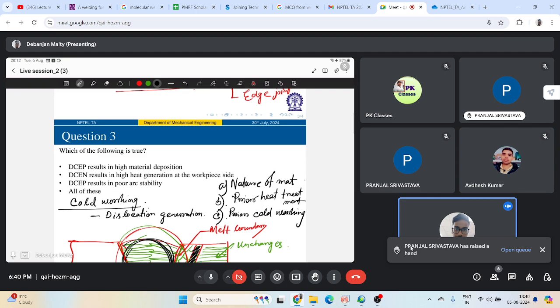Now, you can use some kind of flux that can be used to deoxidize or clean your weld metal, right? So during that point of time, the flux also will melt and solidify and form some kind of slag on your resultant weld metal.